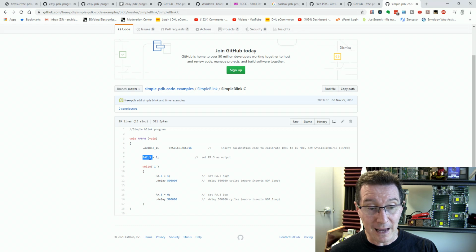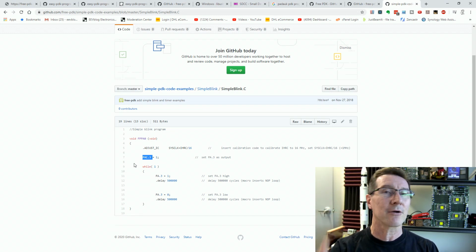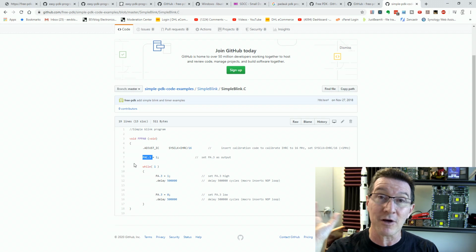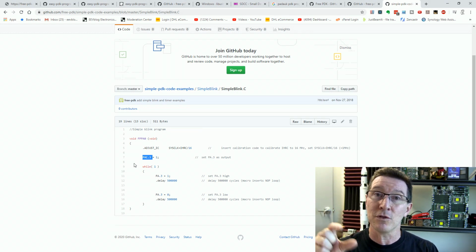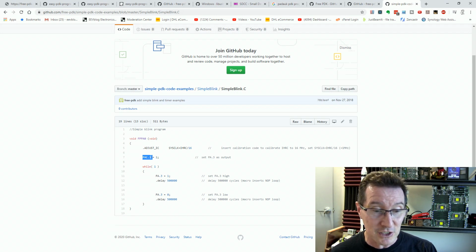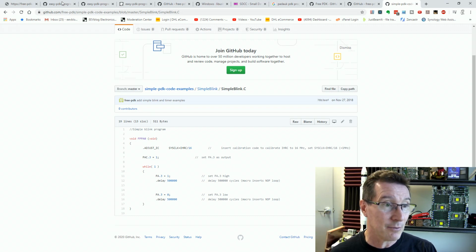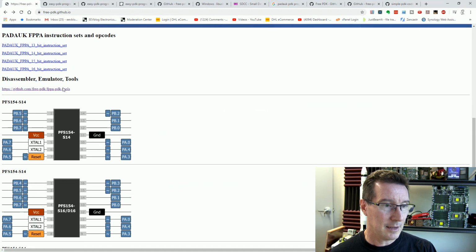Then you've got port A, I don't know what the labeling is. Anyway, it's that port and that pin. So it doesn't matter whether you're using an 8-pin Padauk micro or a 14-pin one or whatever size chip you're using. It'll have all the different ports on there, and you can choose whatever pins you want. So that's actually bit 3 on there, and then you can use the pin out diagram of the chip to translate. We've got that over here somewhere. Yep, there you go, PA3 is actually this pin down here.